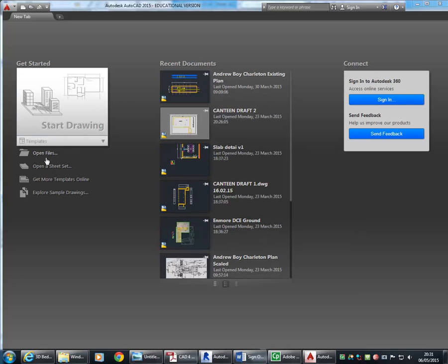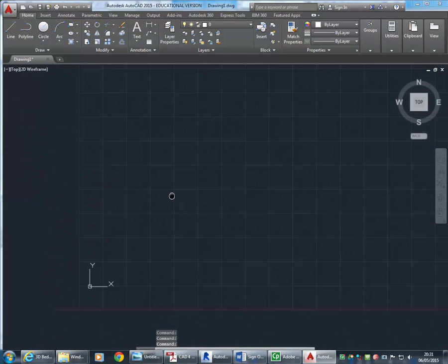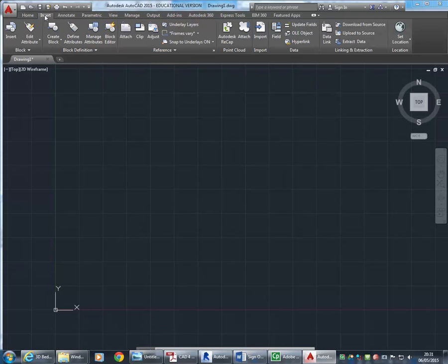into AutoCAD. And really what you're trying to achieve here is a 3D file saved as a DWG file. And this is, apart from anything else, just to reinforce that basic concept that DWG is a more versatile 3D format than Revit, believe it or not. Revit, even though you're working in 3D all the time, it's not really a fully rounded 3D format.